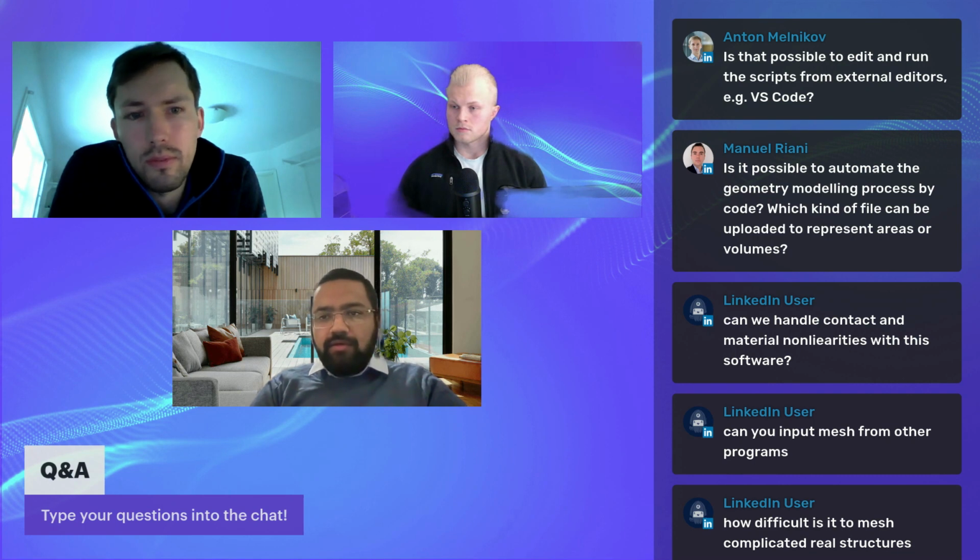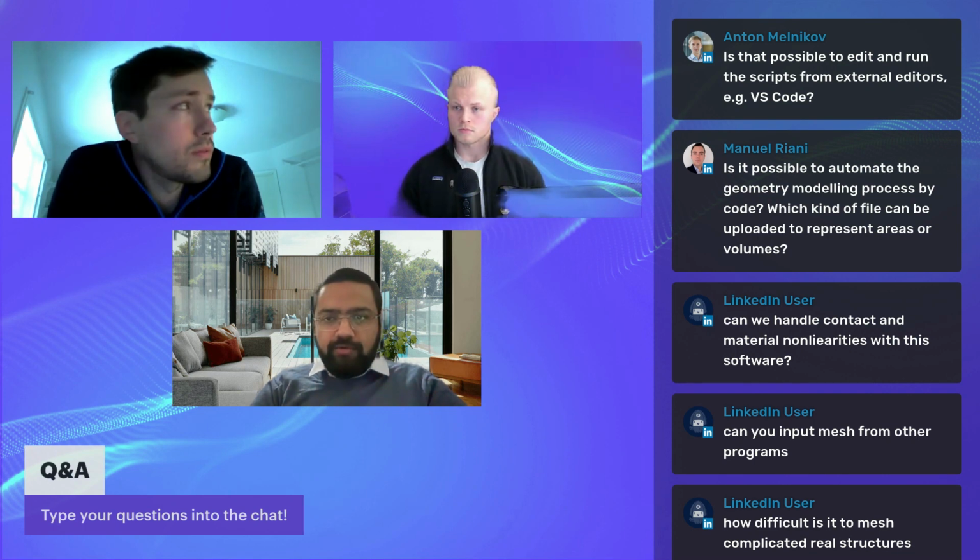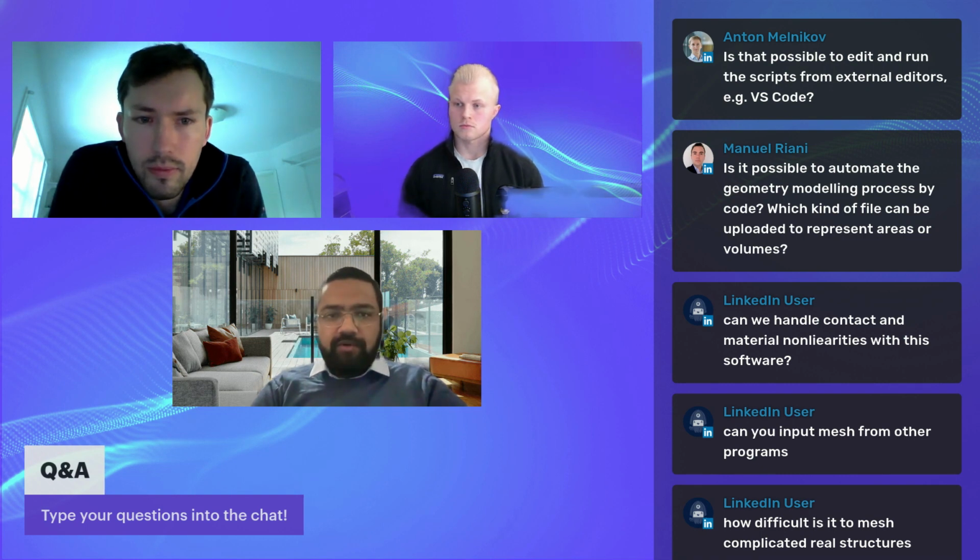That's one option. There are some users who use even more advanced techniques, like using the Python interface to Gmsh. So that's one of the other options. And with the API, if I'm not wrong, it should be even easier in that case. And regarding the kind of file, we support STEP and GDS file formats at the moment. Any CAD software can export a STEP file, and GDS is particularly supported for the MEMS community.